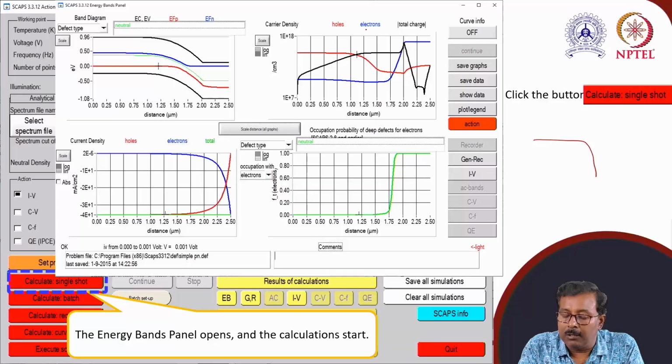And the electrons are low here and increase here. And total charge is calculated in the black color. This is the sum of the moduli of these two charges, just simple addition, red plus blue, red plus blue. In this way it looks like this. So depending on the doping you mention in the layer properties, accordingly the doping profile will be observed here.